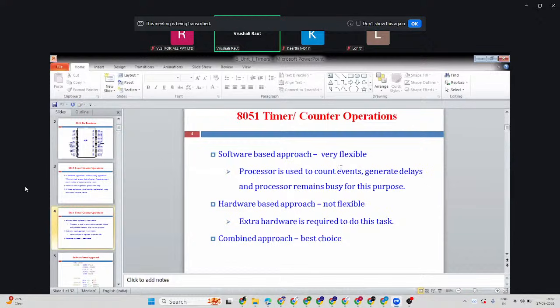But during that approach, continuously who is working? Your processor, your microcontroller, whoever is the computing unit, it is continuously working. Is it right? Are you getting my point? So there is one software approach for generating the delay. Why am I telling this? Because we are going to use the timer for generating the delay. We have to justify why to use the timer for generating the delay.